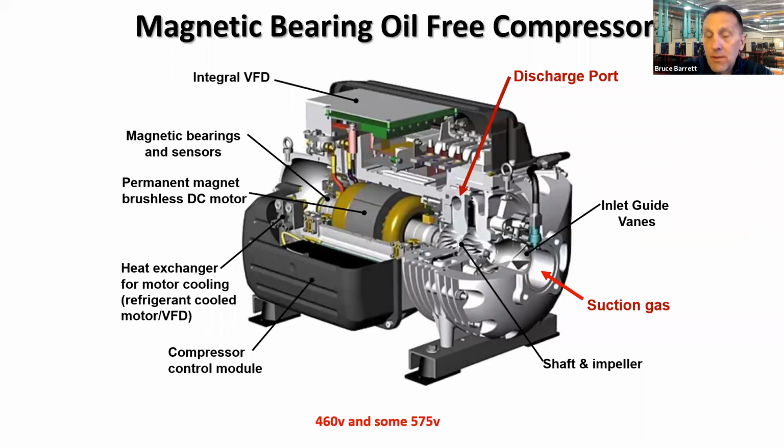Simple diagram of the compressor. They're really light. A lot of aluminum construction, obviously with the magnets inside, you don't want to interfere. So an average 200-ton compressor is going to be about 310 pounds for 200 tons of capacity. So it's really small when compared to a 200-ton screw, probably a tenth of the weight. Right now, there are some limitations on the voltage. 460 volt is the only offering. 208 volt won't exist for a very, very long time, but 575 volt is coming.